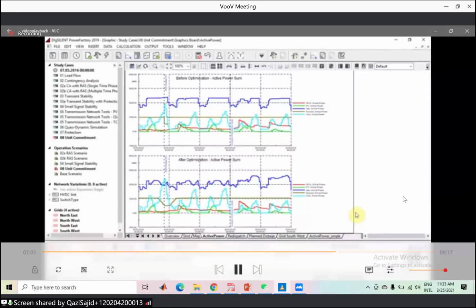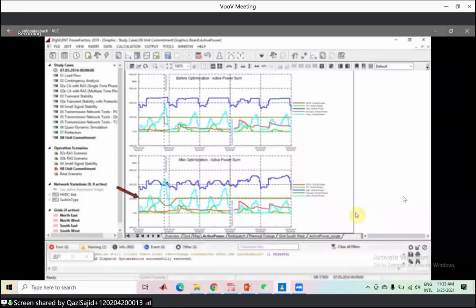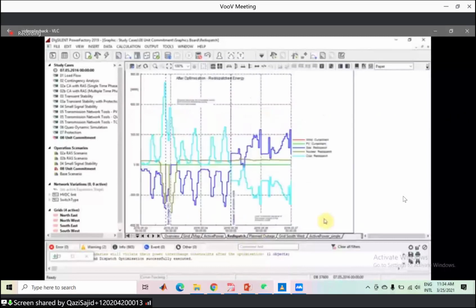We see that the nuclear generation is now at its maximum, and we can see the effect of the increased emission cost after day 3. The generation from coal is reduced for day 4 and 5 of the simulation and substituted by an increase of the gas-fired power plants. This effect can also be observed in this redispatch plot, and the effect of the planned outage of the transformer at the nuclear power plant can be seen. The missing feed is compensated by coal power plants.